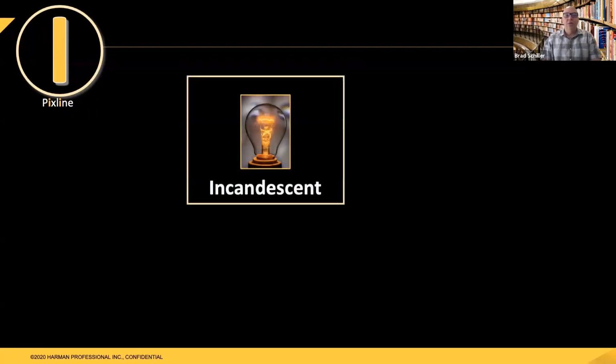All right, so moving into I. Incandescent. Incandescent is where we got started in lighting, really. There were some other things before, but incandescent lights really took off strongly. And it's typically a light source consisting of a metal filament, usually tungsten, which glows while hot when current is passed through it. So we all know what tungsten lights are. A lot of people like the tungsten look. Typically, they have around a 3,000, 3,200 Kelvin color temperature output. So that's what incandescent is.